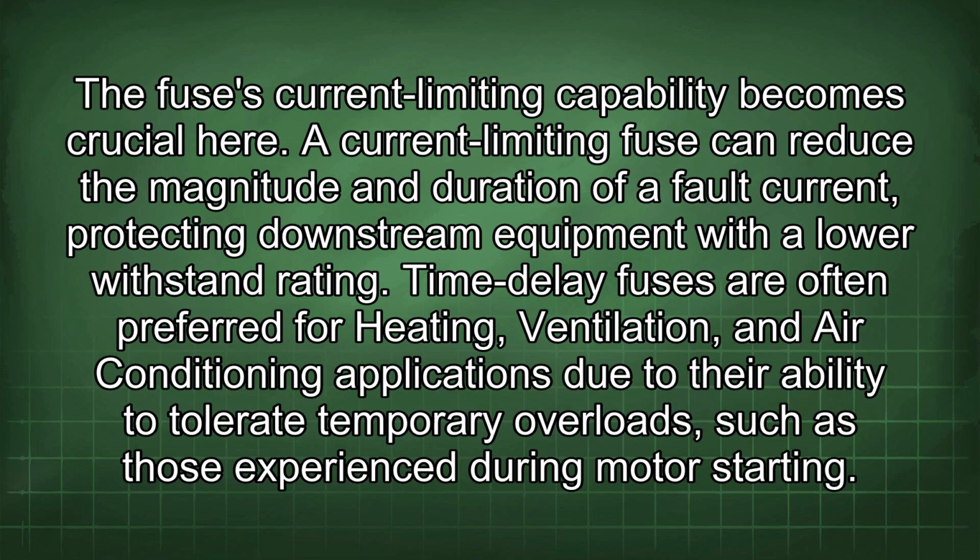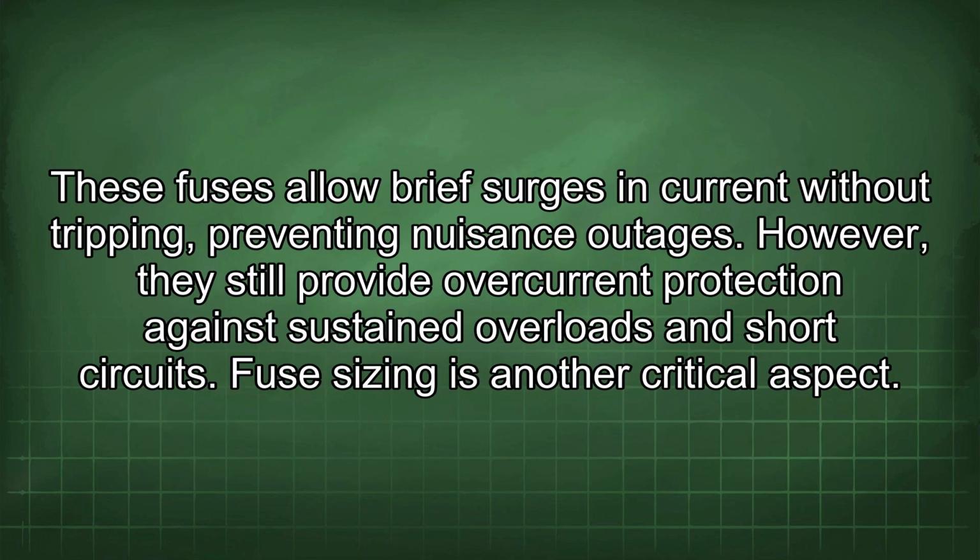Time-delay fuses are often preferred for heating, ventilation, and air conditioning applications due to their ability to tolerate temporary overloads such as those experienced during motor starting. These fuses allow brief surges in current without tripping, preventing nuisance outages. However, they still provide overcurrent protection against sustained overloads and short circuits.